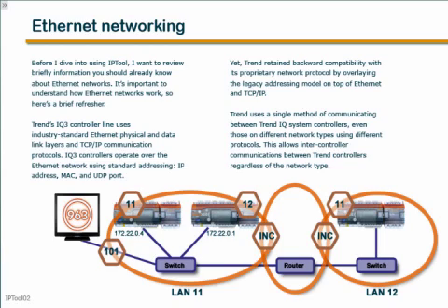Trend's IQ3 controller line uses industry-standard Ethernet physical and data link layers and TCP/IP communication protocols. IQ3 controllers operate over the Ethernet network using standard addressing: IP address, MAC, and UDP port. Yet, Trend retained backward compatibility with its proprietary network protocol by overlaying the legacy addressing model on top of Ethernet